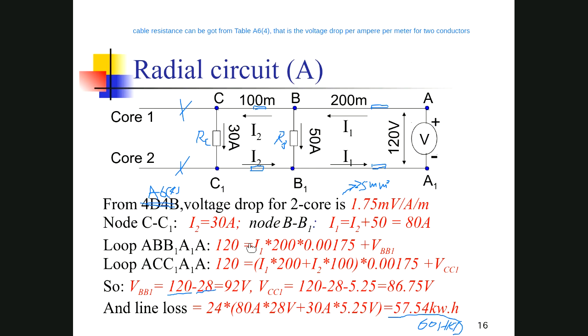So at the top of the building, we cannot use the electricity. So we should use big cables, with a cross-section area of about 120 square millimeters, so that the voltage drop is very small. That's the problem of cable sizing. Next year you will learn about cable sizing based on the principles we learned today. That's the concern about voltage drop issues.